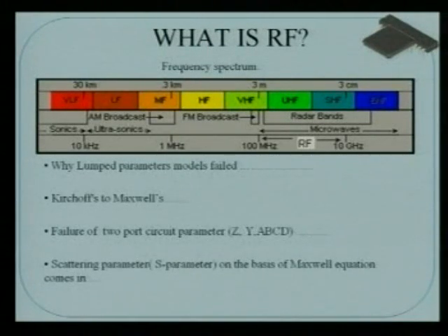And design of these RF circuits in that frequency range is quite challenging, because it was initially thought of doing all the high frequency stuff using exotic processes like gallium arsenide based or some group 3 compound based IC, which is expensive. But now even in silicon, the cutoff frequency can go up to 100 gigahertz. So it is now possible to realize even silicon based RF circuits. So whatever we will learn today is basically a very cost effective silicon based RFIC design, or more precisely it is RF CMOS.